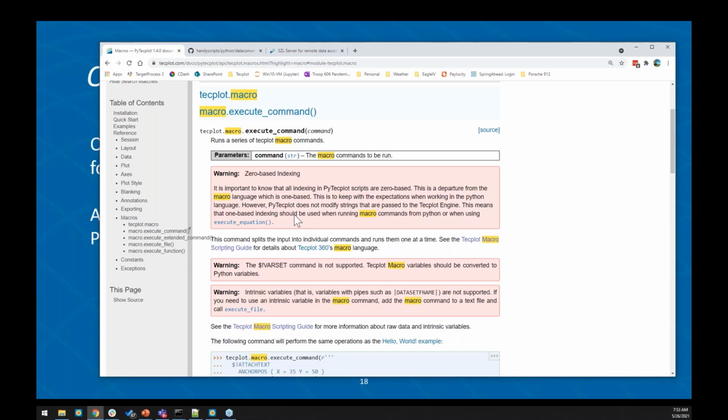So I don't know that I'm 100% following, but it sounds like can you run a Python script and then append to it by recording additional commands? And the answer is really no. Yeah, I think when you record, it's going to record to a new file, or if you select an existing file, it's going to overwrite it. So you're going to have to append the new commands yourself. Yeah. Okay, and one more question.